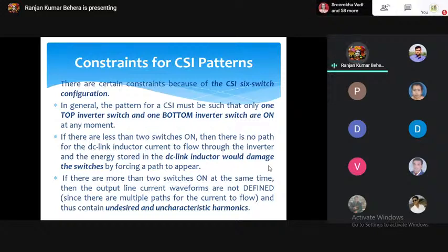That leakage current, due to the inrush current like the inductor, impinges the current into the channel formed between N and P. A large amount of current will come through that channel, there will be a hot spot, and that switch will be damaged. That is how the switches get damaged when you don't have two paths, one switch from the top and one from the bottom.